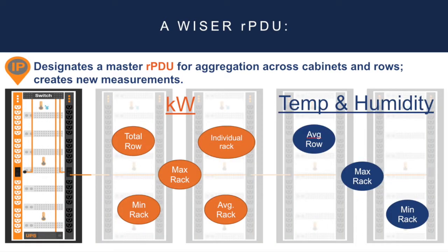On that same note, when that happens, you see not only individual PDU readings, but you also, as mentioned, capture totals, maximums, and minimums. We're not only interested in the individual readings per PDU or per cabinet, we want to understand power and cooling profiles across the entire space. Do I have hotspots? Do I have more dense areas and less dense areas? It's through the summation and these calculations of maximums, averages, and totals that we as users get a better statistical grasp of the complicated ecosystem that we're working with.